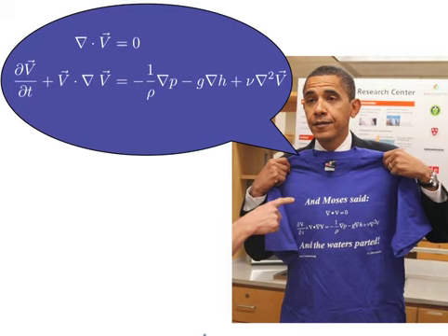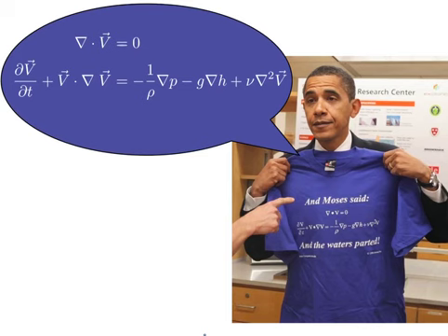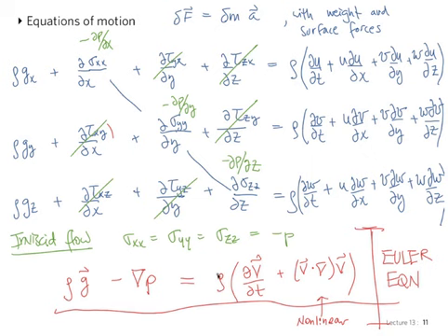So you see they're a little bit different. Let me go back. The one in red is the vector form of the Euler equations. That is the specific case of inviscid flow. Now here we have the vector form of the equations for the viscous flow. They're turned around. What we have on the left here is the acceleration. In this case, it's on the right, the acceleration, right? With what we call the local acceleration, or the unsteady term, and what we called, if you remember, the convective acceleration. We wrote the acceleration in this way simply by doing chain rule. I hope you can recall that.